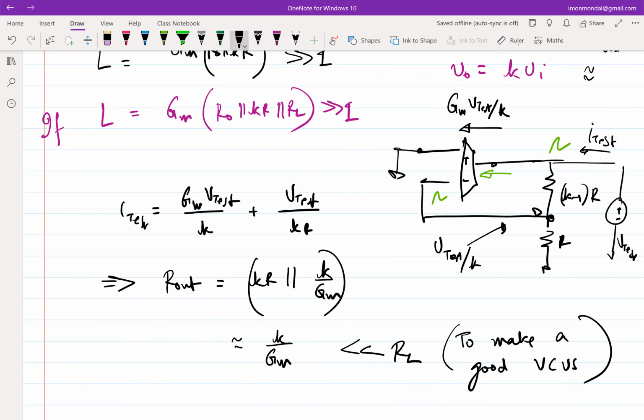And now coming back to our discussion of the MOSFET, we wanted that PMOSFET because we wanted to ensure that this error amplifier is strong enough to kick the loop in the right direction. Kicking means, in this case, you need high gain. Okay, and if you need high gain without using a large power supply, you need some active load, right? Because ultimately the impedance looking into the drain of a transistor is large, so we wanted to leverage that.